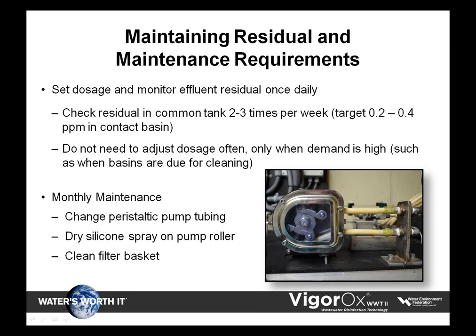The monthly maintenance only takes really a few minutes. We change the peracetic pump tubing, we put dry silicone spray on the pump rollers, and then clean out the filter baskets.